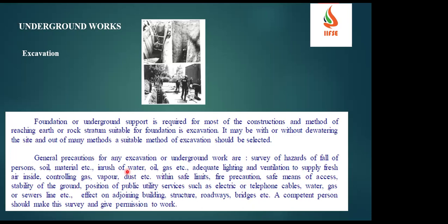So if you see in underground works, a foundation or underground support is required for most of the construction. The method of reaching earth and a rock stratum suitable for foundation is excavation. In the sense, until you get solid soil, we will do the excavation. It may be with or without dewatering the site, and out of many methods, a suitable method of excavation should be selected. It sometimes depends on groundwater availability. Within a few feet, you will get water logging in the excavation. Based on that, we have to choose the suitable